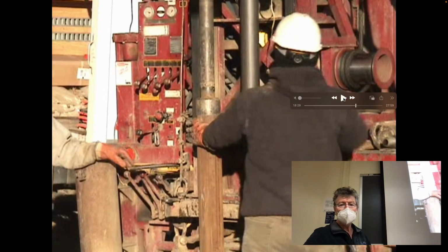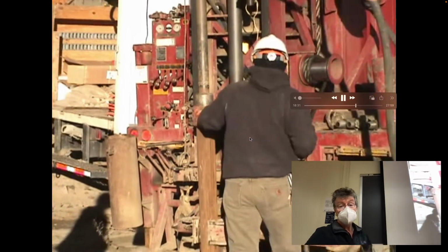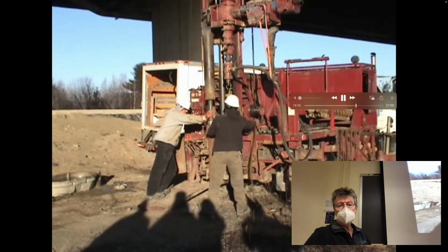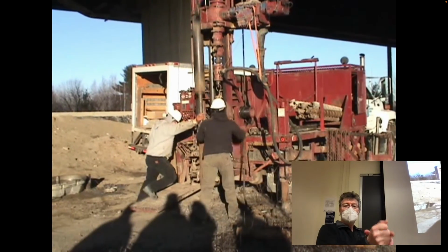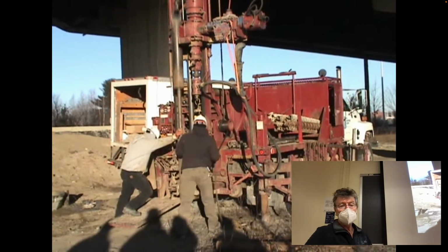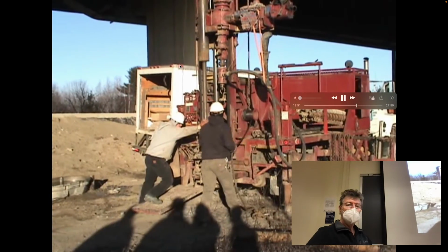All right, so you didn't see the split spoon, but down at the bottom of the hole is a sampler. The sampler we talked about that we used in sand and gravel, which is sitting on the bottom of the hole. And now it's being rammed into the bottom of the hole by this monkey hammer. I call it a monkey hammer. All it is a weight, a capstan. When you pull on the capstan, it tightens around the capstan, and therefore it gets lifted up into the rig. When you let go of it, it falls under gravity, and the specific weight of this falling through a specific height is what you measure.